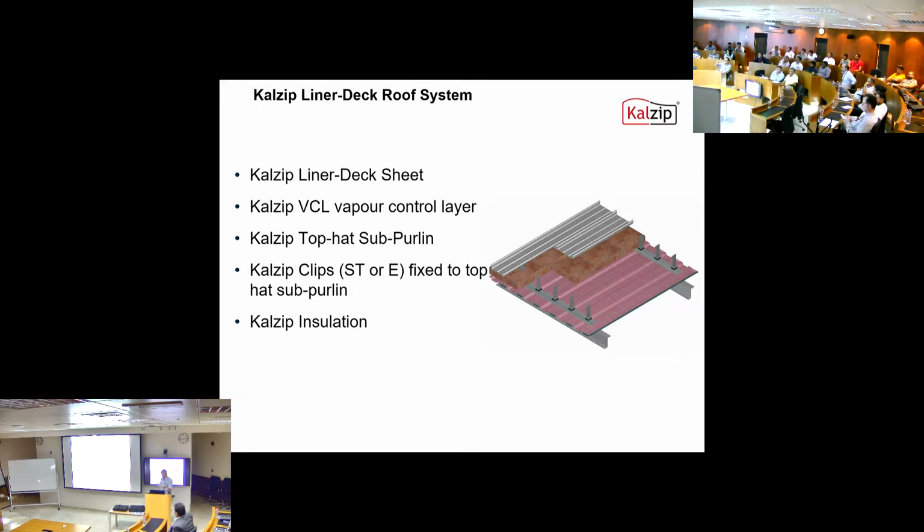Lateral move. Yes. In this direction here, L over 200 between purlin spans. In the measure direction, yeah, L over 200. Along with the purlins, not necessary. That's right. Excellent. Okay.